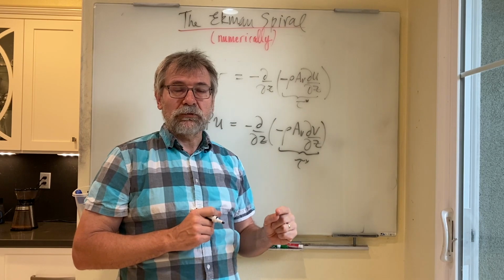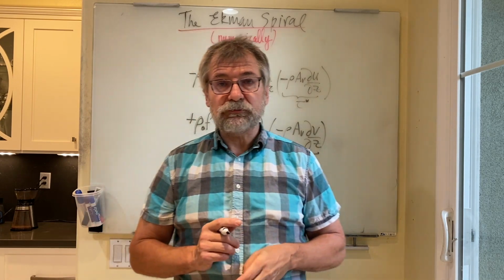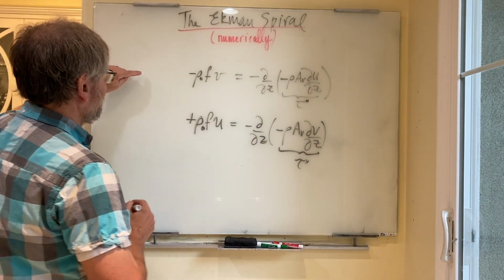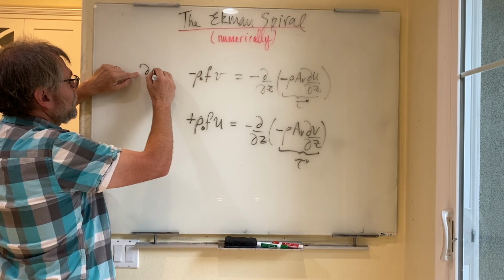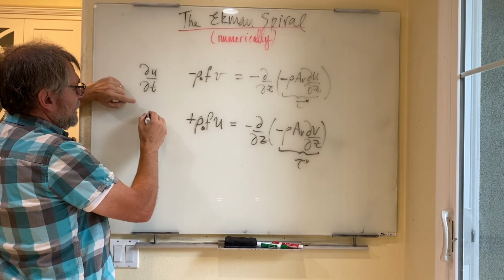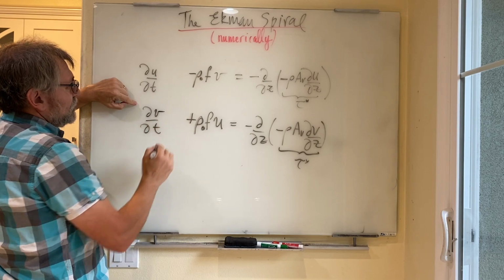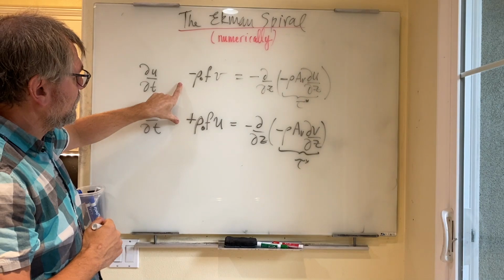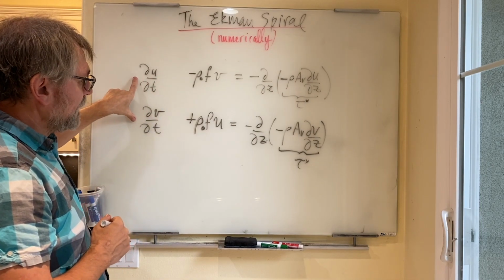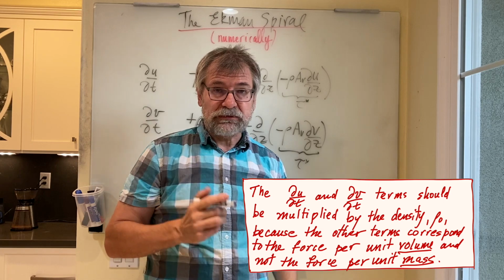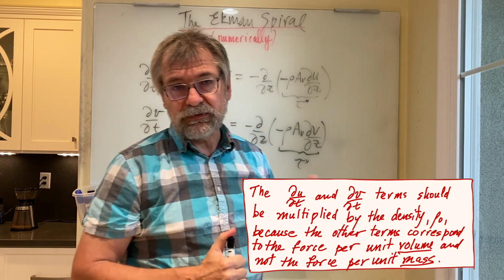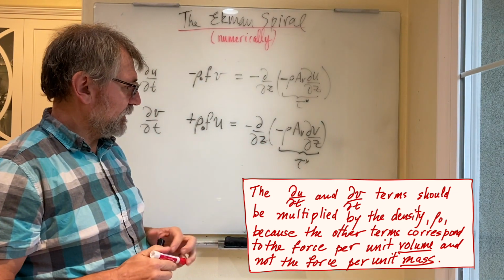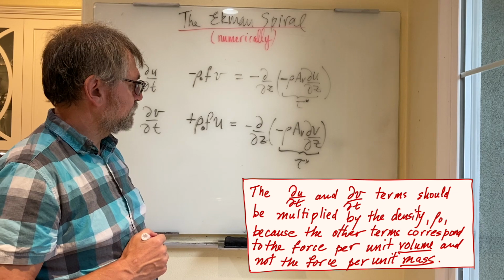This time, to solve it numerically, we're going to go back to the time-dependent form. Remember, we solved the steady-state equations before, and we neglected the time derivatives. Now we're going to bring those back from the dead. In this equation there was a du/dt, and in this one there's a dv/dt. So we will retain these time derivative terms. We're not going to keep the nonlinear terms, assuming that they're small, but we will retain the time dependence and solve the time-dependent problem instead, which I think is going to be more illustrative, and in some ways makes the problem a little easier than solving directly for the steady state.